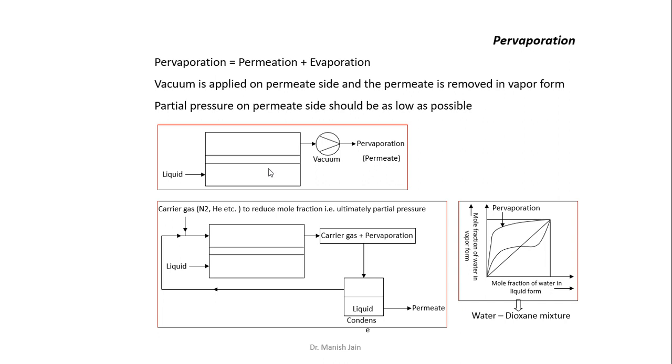So the diffusivity of feed species in the membrane will reduce significantly with reducing temperature. Basically, this process can only be used to separate out compounds which are present at only 1%, 2%, up to 5%, up to 10% in the mixture. This process cannot be used to separate out any compound which is present at more than 10% in the mixture.